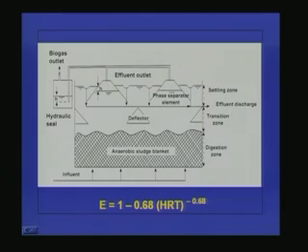And as we see, some portion of the liquid and some microorganisms or flocks which are not yet removed from the system will be coming out through this portion. We can see here the cross sectional area of this portion is very less compared to this portion. So what will happen to the velocity of the liquid coming out through this portion? The velocity will gradually decrease as the cross sectional area increases. So because of the velocity gradient and due to the settling velocity, the microbial flocks will get settled here, and only clear liquid will go up.